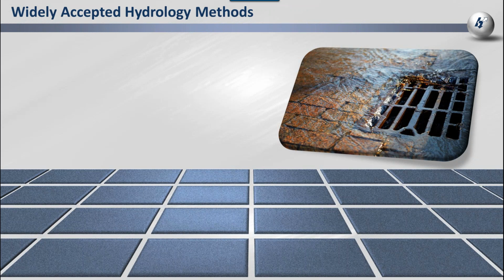Rainfall interception from depression storage, infiltration of rainfall into soil layers, percolation of infiltrated water, interflow between groundwater and the drainage system, and nonlinear reservoir routing of overland flow. Now, these processes are achieved by dividing a study area into a collection of smaller subcatchment areas and basins, each containing its own fraction of pervious and impervious sub-areas. Overland flow can be routed between these sub-areas, between subcatchments, and between entry points of a drainage system.